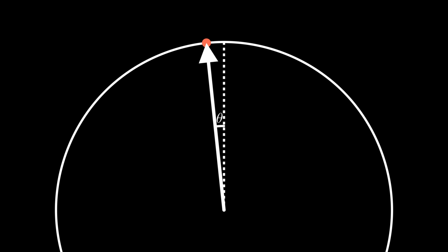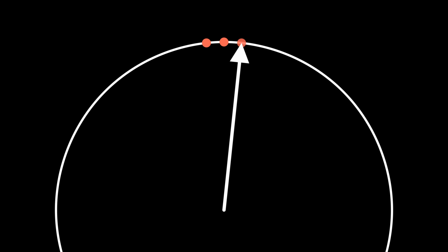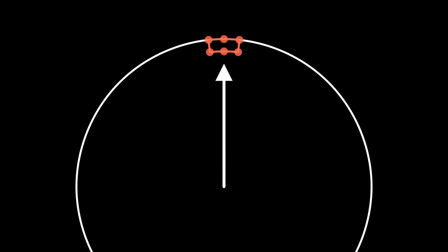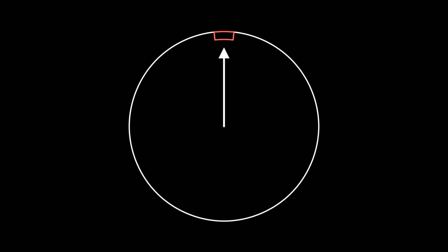It uses a radial vector to specify the cylindrical body, and then defines the first cutout, which will be patterned later. We define the cutout shape in polar coordinates for design intent, a radius and angle for each point, and then use basic trigonometry to convert to Cartesian for the internals. Once the points are defined, it creates an arc with the top 3 points as inputs, a second arc with the bottom 3 points as inputs, and 2 straight lines connecting the outer points. That shape is then extruded into a solid body.